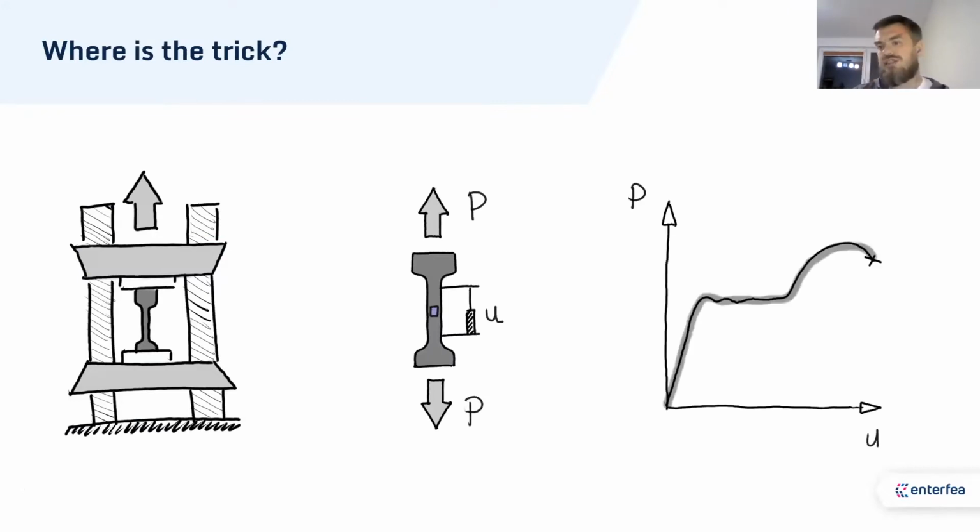And while the chart actually shows you the relation between force and elongation of the sample, we could easily transfer it to stresses and strains simply by dividing by length, dividing by cross-section area, and so forth. So you will notice that I have a yield strength here that's 235 in normal temperature, right? So you could think, yeah, but then somewhere after the plastic plateau, the curve increases, the material strengthens.